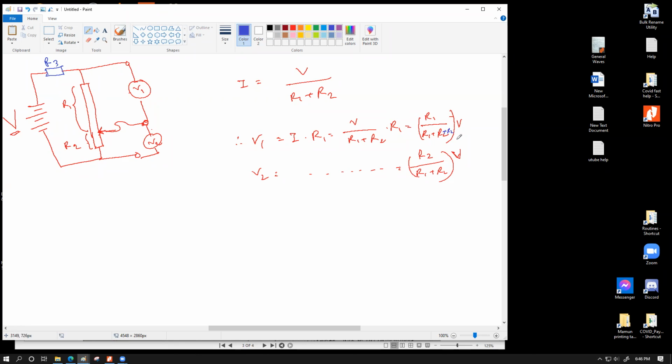The way this fraction works is that you place the resistance between the two terminal points. So over here, this is one terminal, and this is the other terminal. This part of the resistance goes on the numerator, and the entire resistance of the circuit goes on the denominator. So I'm going to write R relevant. This is just some equational format that I came up with to make sense with kids. You should never write this in your actual answers. I can write R relevant divided by R total. To get this ratio and multiply it by the source voltage, you basically get the voltage output of the relevant